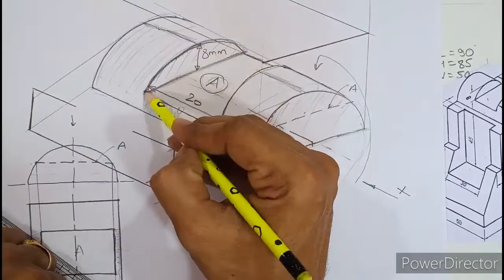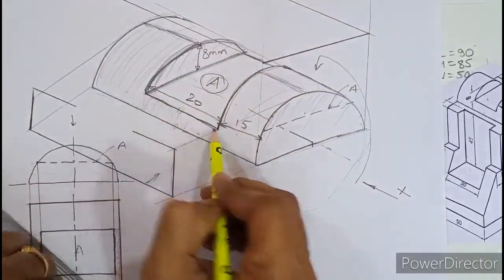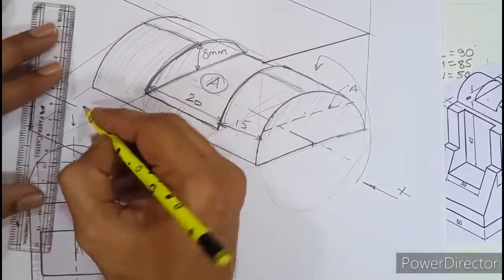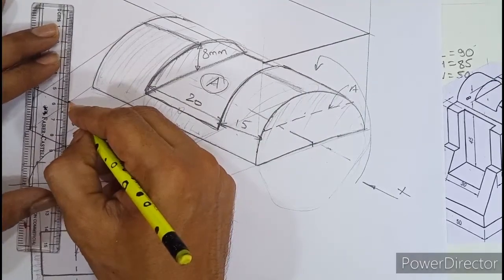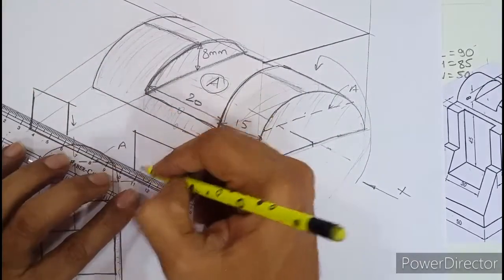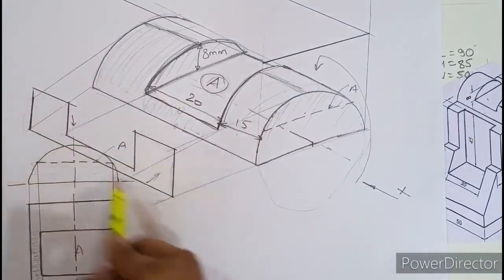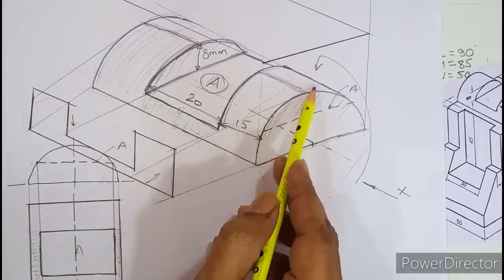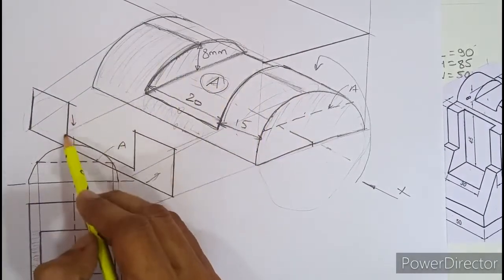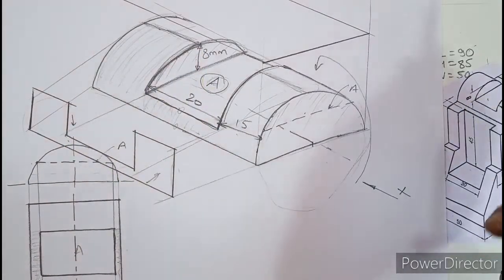Then this circular edge on both the sides will be seen as a vertical line, and then you have to close this one. So if I project these points down from here on both the sides, you can see that the surface goes down like this, and we need to close it. So that is how a C type is seen for the semicircular surface in the side view. So this vertical line, small line, is 8 mm deep. So that is how the side view of a cylinder is seen.